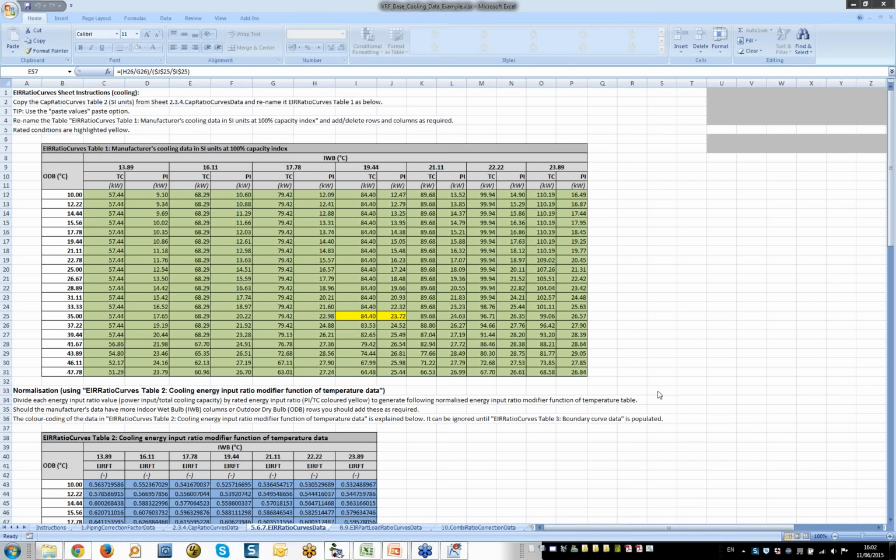Is there a way to import a model from SketchUp? There is. If you've got a plugin that generates GBXML, and I know there's a plugin called GModeler, you can use that to generate GBXML data, and then DesignBuilder can read that GBXML in.